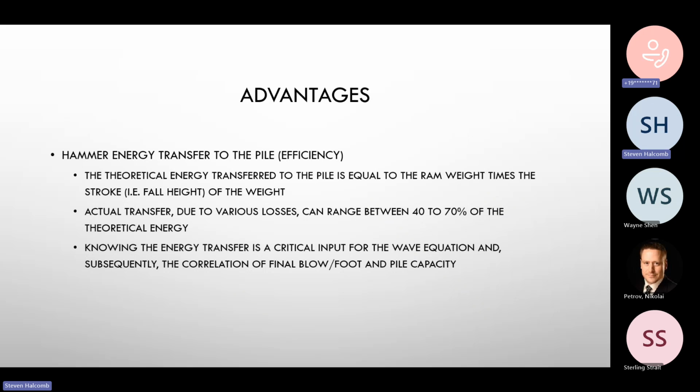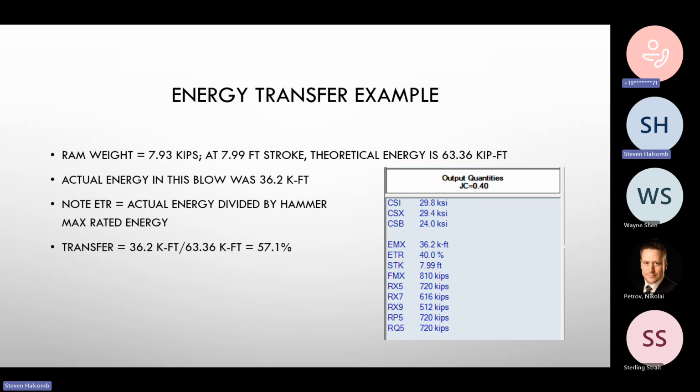And that's one of the big reasons, aside from soil properties, that pile driving formulas are pretty limited and have such high factors of safety, because you don't actually know. If you have a rough idea what your hammer is, or know the range that you would expect, the pile driving formulas can get a little closer at times, but you have to know ahead of time.